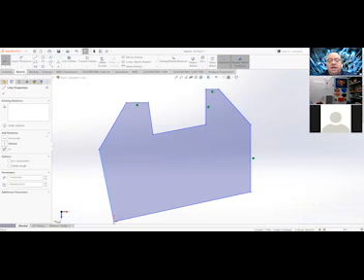So once I select the line, I look on the left side panel, and there's a vertical and a horizontal constraint. There's also a big giant anchor point. That anchor point locks the line so you cannot move it. And occasionally somebody will do that and they'll forget they've locked it and they can't figure out why their drawing won't move to where they need it to. So just be aware of that fixed one.